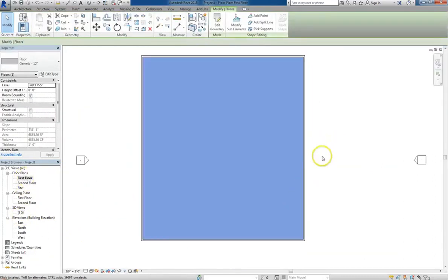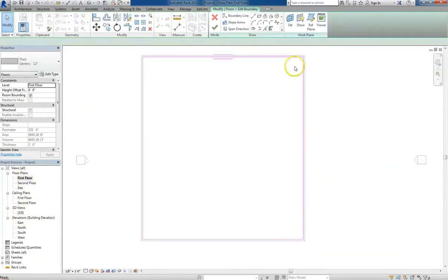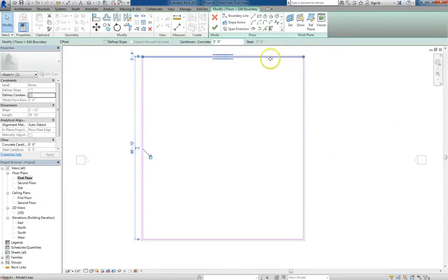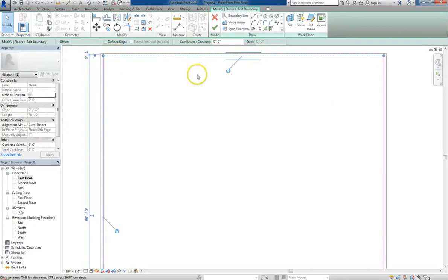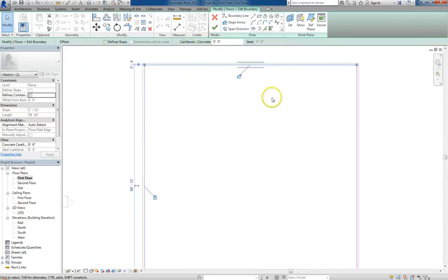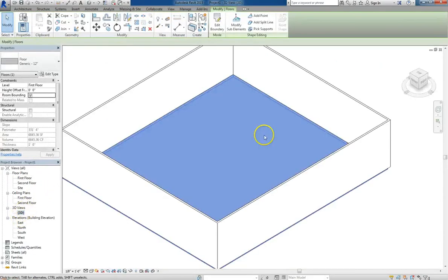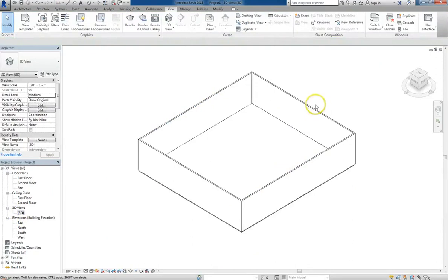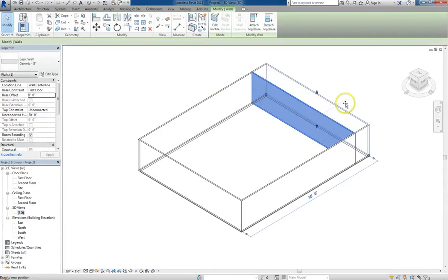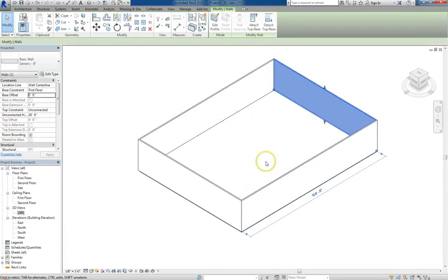If you put a line over any sort of element, a wall, a door, anything while you're in sketch mode, then that element tends to lock on to the line, which makes things a lot easier when you're going through. Because now, if you're working on your project and your boss tells you to extend the wall, then just moving that wall out will adjust everything.